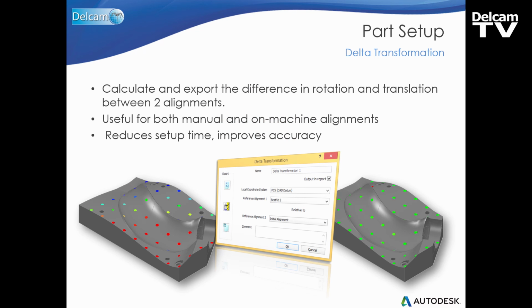Okay, so our solution in PowerInspect is our delta transformation functionality, which allows you to calculate, then export the difference in translation and rotation between any two alignments. With PowerInspect, you can do an approximate alignment by eye, then probe your part using either an on-machine probing tool or a portable CMM, and then use this delta transformation process to tell your CNC machine to account for any small misalignment. This means what you're effectively doing is moving your NC code to the part rather than moving the part precisely to your NC code.